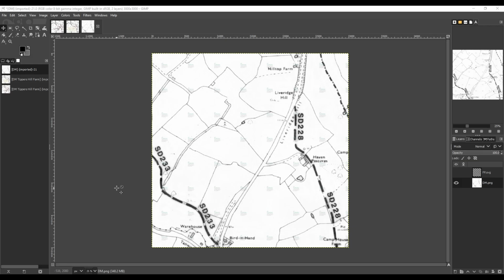So I need to make a few points about this extract from the definitive map. The first is that it's exactly a kilometre square and exactly 3000 pixels square. That means it's 3 pixels per metre. The other point to make is that it's perfectly aligned on an OS NGR 1 kilometre square, and we'll use that information later. That's going to be quite useful.